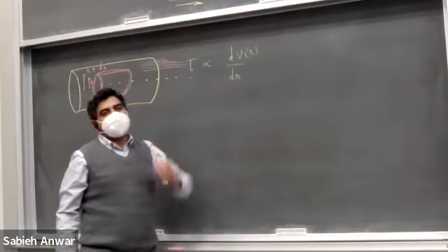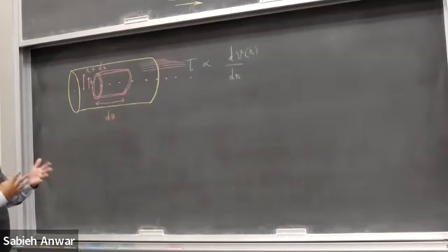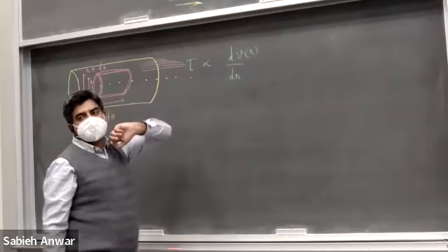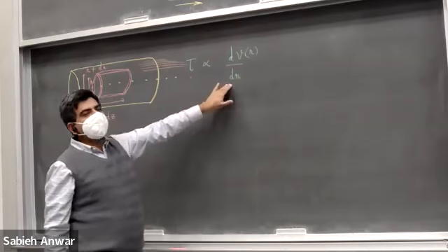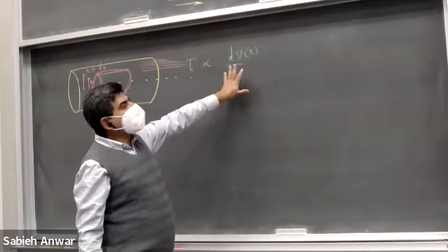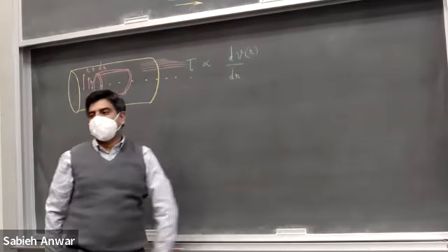So what is v here? V really is the displacement with respect to time, the rate at which a layer is moving at a distance r. All right. So I could come up with a relationship exactly analogous to the stress-strain relationship for the solid. Tau, the shear stress, is now proportional to the spatial rate of change of speed.